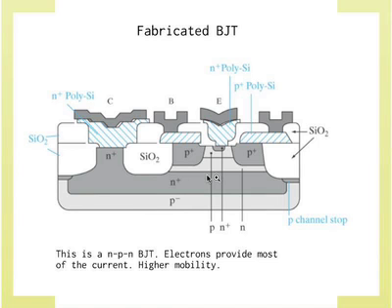Now the base is right here, the contact's right here, and that's the base. This thin region right here forms the transit region for the electrons in this case. We'll go through the injection in a second, but think about that as the base. Then you have the emitter here. Sorry, the base is P-type, the emitter is N+, and is contacted through polysilicon.